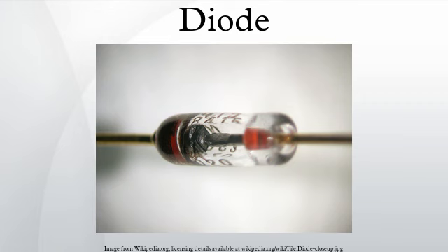Waveform clipper. Diodes can be used to limit the positive or negative excursion of a signal to a prescribed voltage. Clamper. A diode clamp circuit can take a periodic alternating current signal that oscillates between positive and negative values, and vertically displace it such that either the positive or the negative peaks occur at a prescribed level. The clamper does not restrict the peak-to-peak excursion of the signal, it moves the whole signal up or down so as to place the peaks at the reference level. Abbreviations: diodes are usually referred to as D for diode on PCBs. Sometimes the abbreviation CR for crystal rectifier is used.